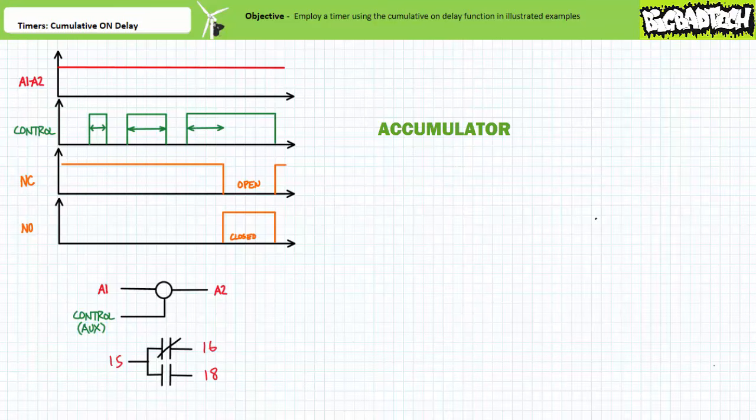Ordinarily, I'd give you a link to this lecture, but it has nothing to do with what we're talking about. Accumulators in this sense mean a running tally of how long the controlling input has been asserted. If the timer is ever completely depowered, this serves to wipe the slate clean and reset the device. Note, for the purposes of this general lecture, I'm trying to avoid getting entangled in manufacturer specifics. It is your responsibility to interpret the timing diagram for your particular multifunction timer of interest.